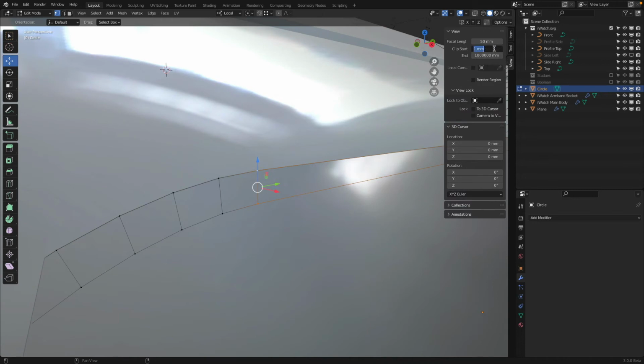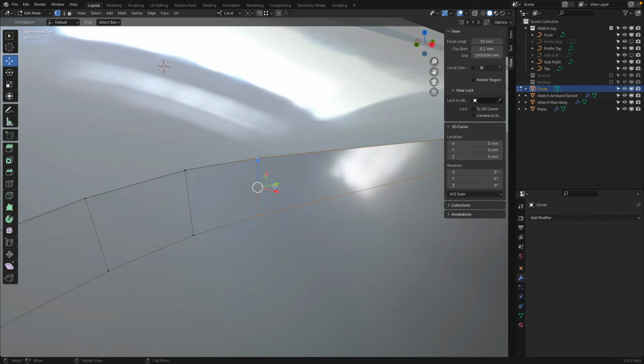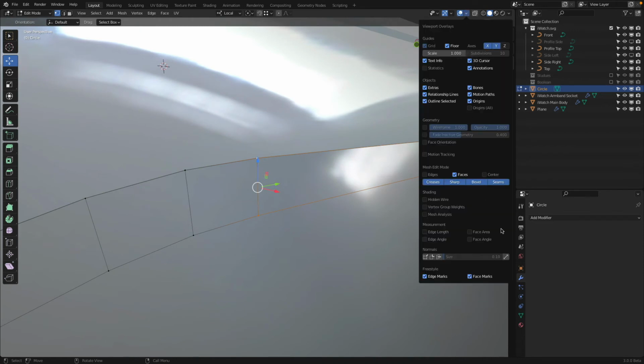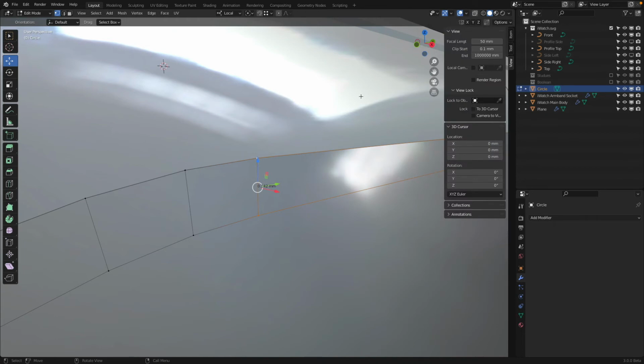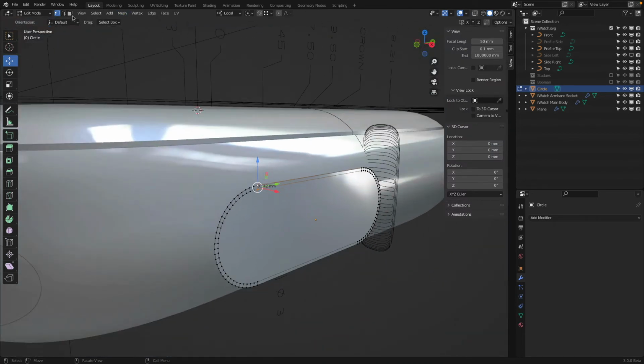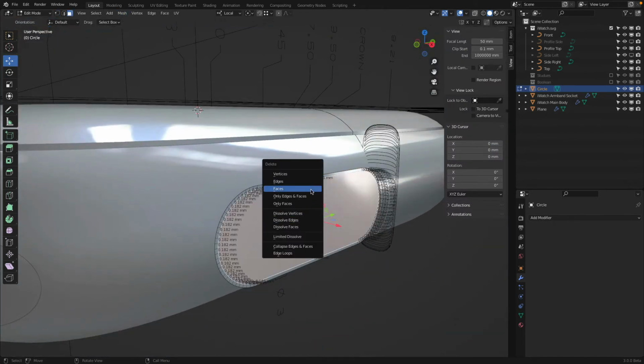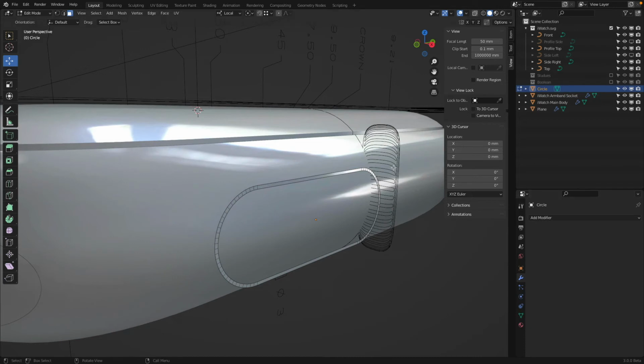We can get really close if we set the clip distance to 0.1 millimeter. And then let's tell me 0.1, so 4. So really kind of like 1/10, 1/15 of a millimeter. Goody. That's perfect. This now we will delete.